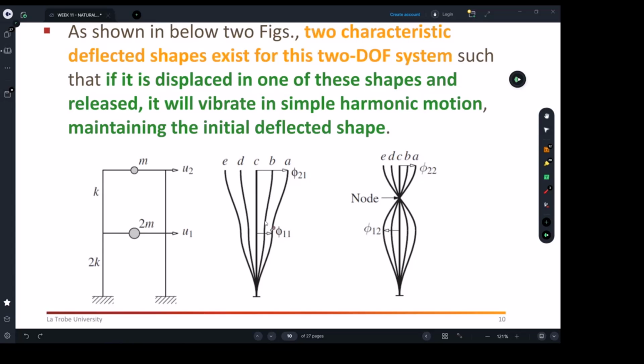But I just want to understand mode shapes. Any multi-degree of freedom system has a number of mode shapes. Now, if we have defined the floors by lumped masses, and those lumped masses were 3, then you're going to have 3 mode shapes. If the lumped masses are 2, you're going to have 2. If you have 10, you're going to have 10.